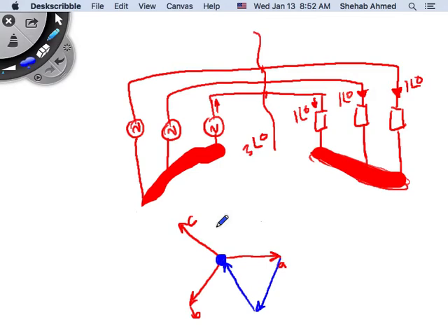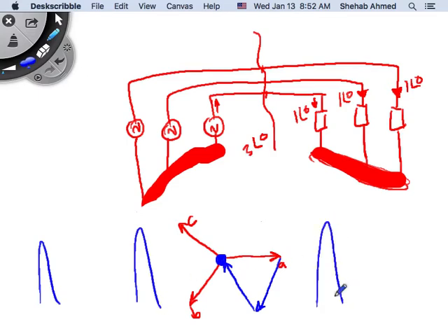And that's why when you're driving along at transmission towers, you will see 3 conductors strung, or 6 if it's a double circuit. So typically 3 if it's a single circuit tower, and we'll talk more about that, or if you're transmitting 2 sets of 3-phase, you will see 6 conductors. Sometimes you will see a ground connection, but the ground is different. It's a safety issue versus the neutral wire. So neutral connections are not typically used at the transmission level.